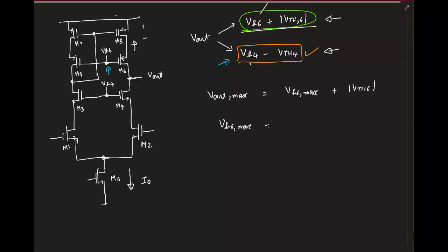the transistor M6 is biased at a current of I0 by 2. So to maintain this current, the source voltage here will also increase. The source voltage of M6 is the drain of M8. So M8 will limit it. And what is that voltage now? Can you tell me?